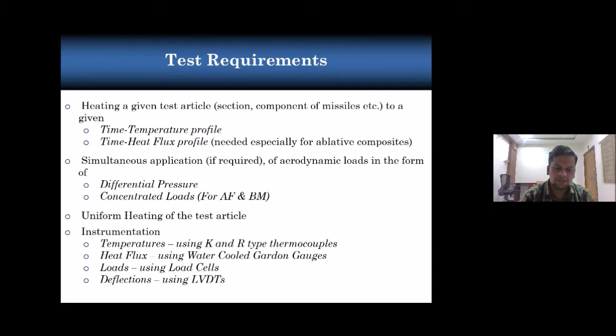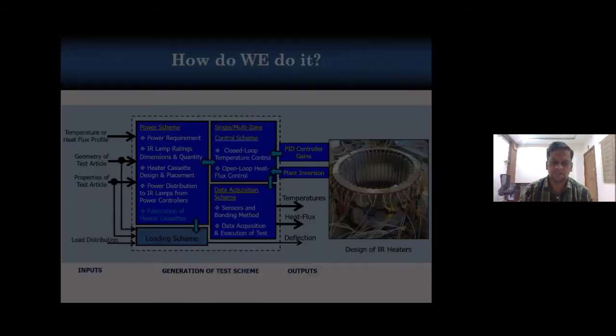For instrumentation, we mainly use K-type and R-type thermocouples, heat flux sensors, Gordon type water cooled thin foil heat flux gauges, load cells, and deflection measurement using LVDTs. Load cells measure the applied concentrated loads.